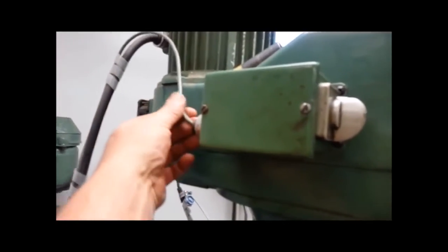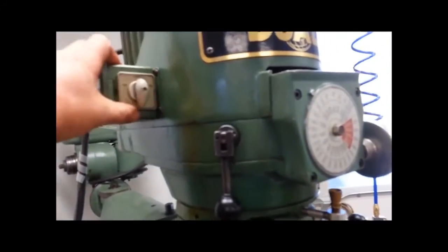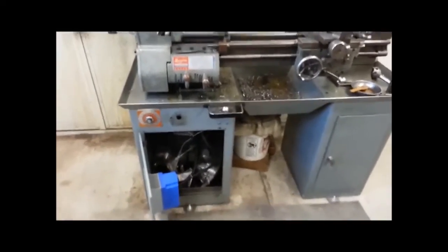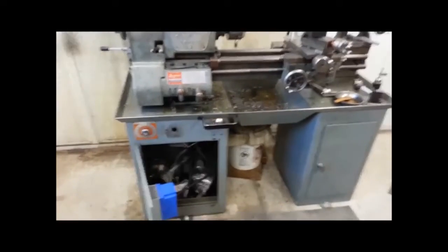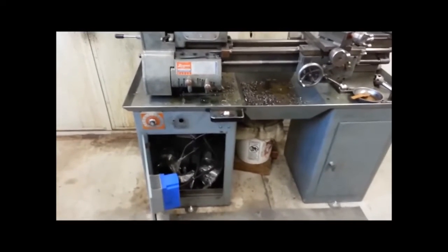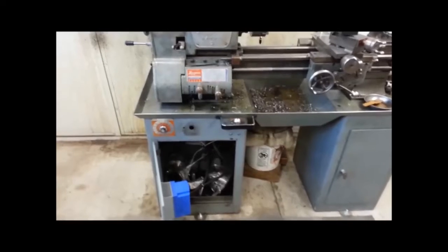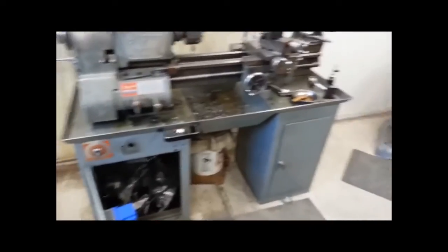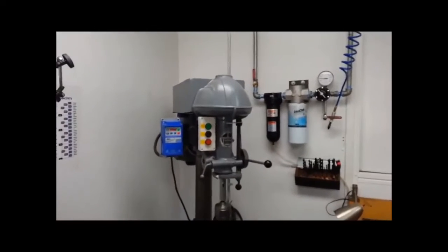I'm just running a very small Belden cable off of it with 2 conductors in it, to 1 pole of the 3 available poles in the factory drum switch to operate the VFD. Same there, just run 2 conductors over to that switch, and that one is programmed to use a speed reference. And speed reference is a programmable parameter, and the speed reference is a 10K pot. That's that little potentiometer you see there on the dial. And that's maintained contact. That one over there, momentary contact.